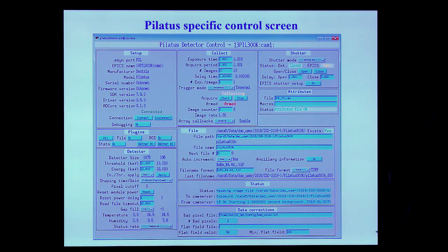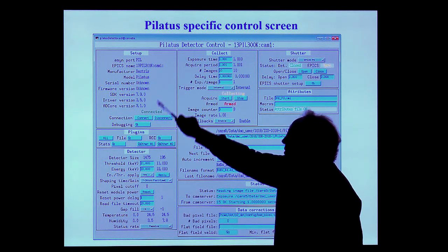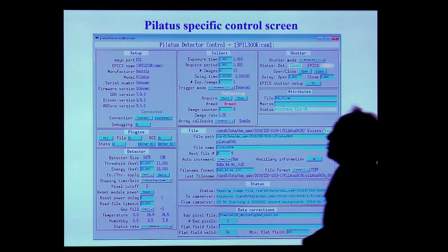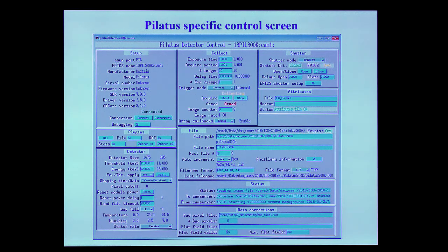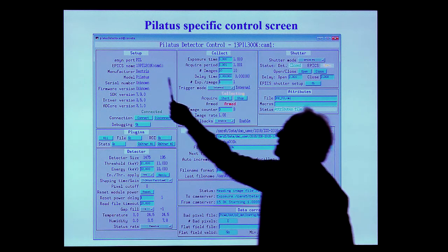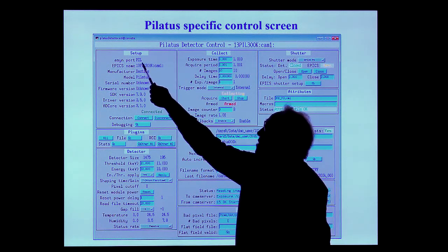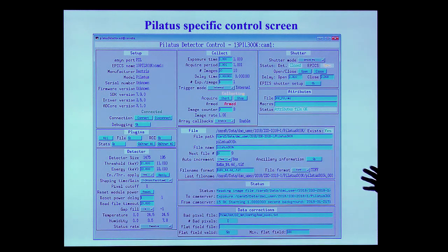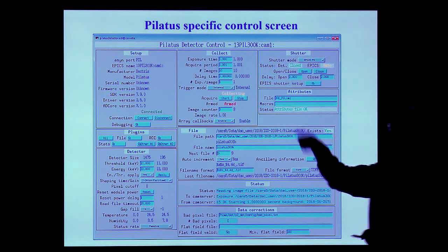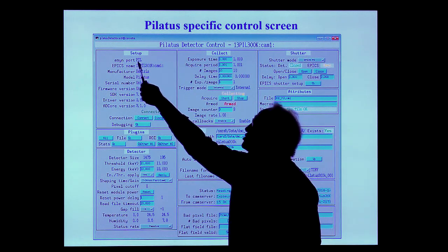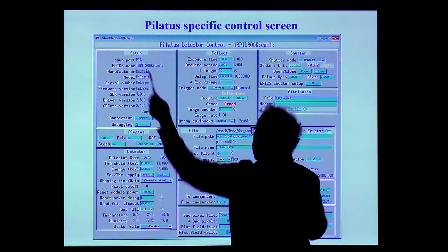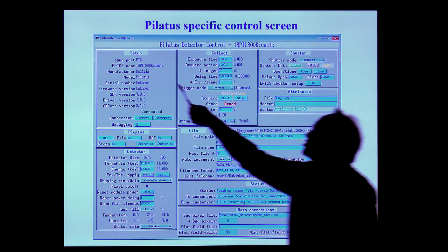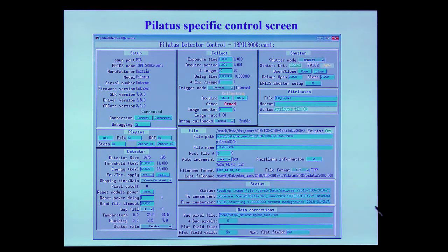I did want to point out that there are these standard blocks here. Like this one is a block that has all this information about the setup of the detector, and every detector and every plugin has a name for that. It's called the ASYN port. And you do need to know what that is, because if you want to change your file plugin from getting data directly from the detector to getting it from a plugin, it's this string that you type in to say, where do you get your data?